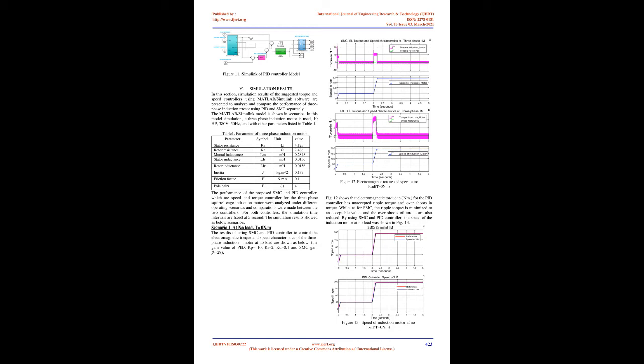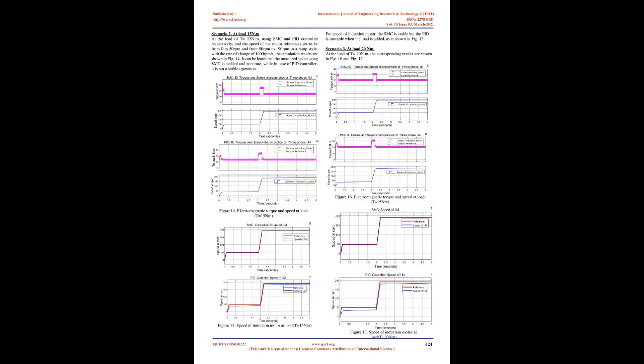A PID controller was used to control an induction motor, modeled in Fig 10 and Fig 11. The analysis of its performance and the comparison with the SMC controller will be discussed in the next section. The equation of the PID controller can be explained as load torque ripples disturbances. In sliding mode control, the system is well controlled in this manner that the tracking errors, and their rate of change, constantly flow in the direction of a sliding surface. The sliding surface is defined in the state space representation by the equation.